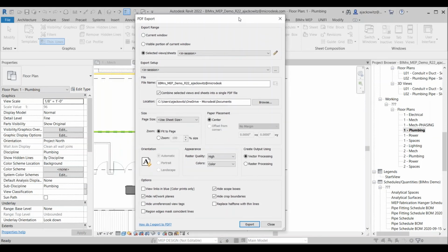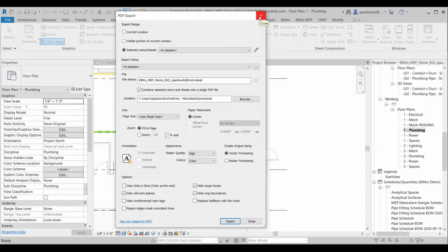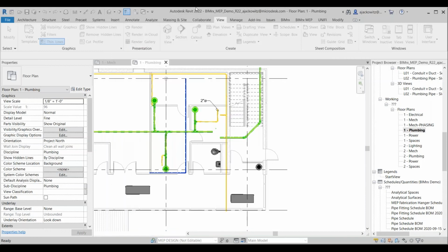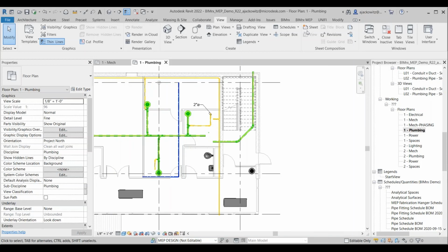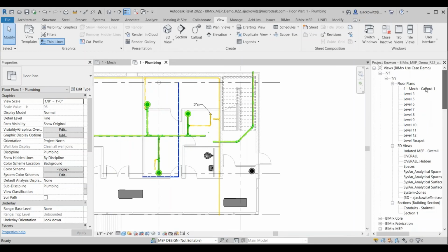It's not going to be a pain to have to do the Control P, print through different sets, have to accept every slight name change for a set. You can lock that all in and just let the thing run for either a full set or for separate sheets as well. So again, another one of those things, kind of long time coming, but can trust that it's built into Revit now for some of our sheet sets in printing.